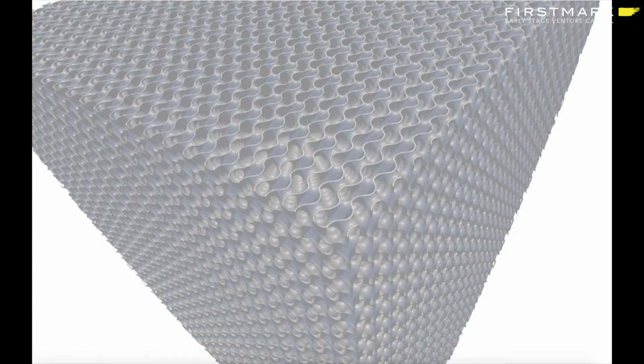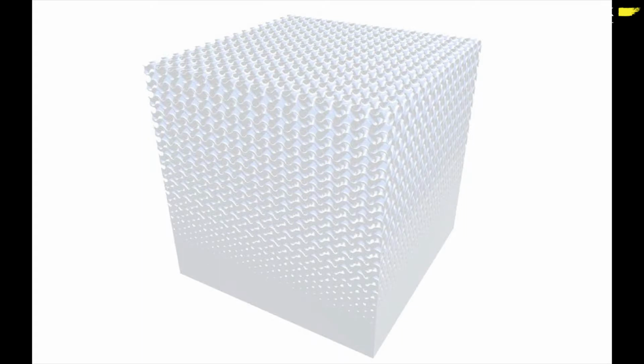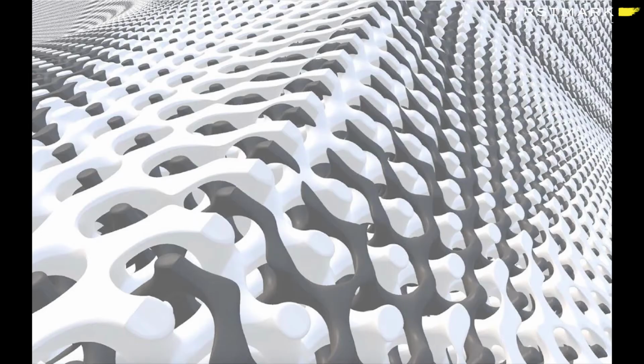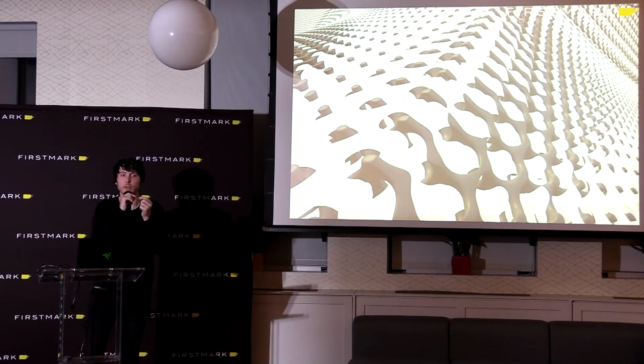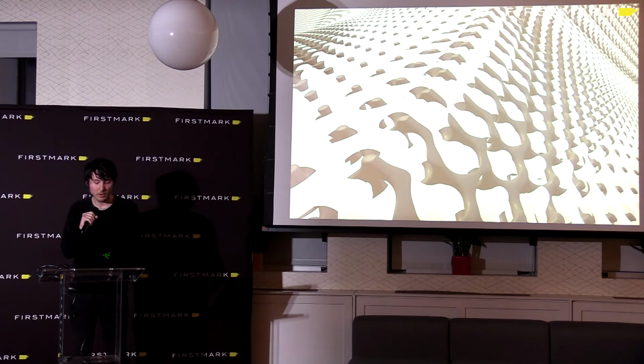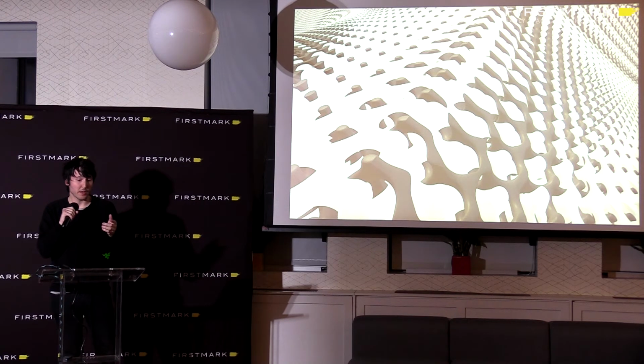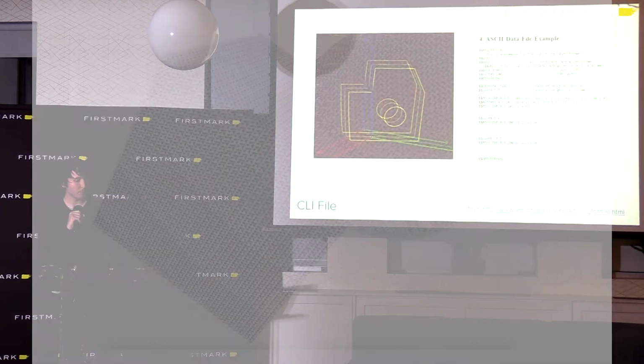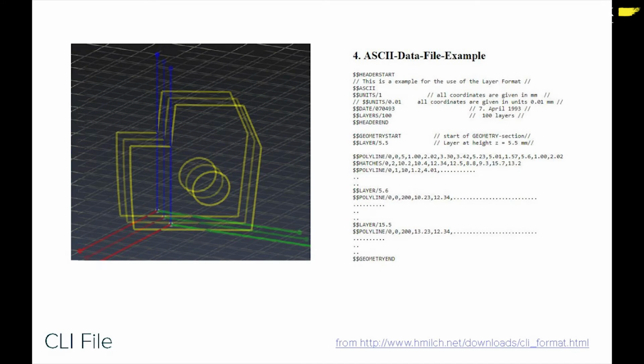And then we can also grade our structure. But something like this would probably be impossible to mesh, a structure where you have a 300 millimeter box with a 0.5 millimeter unit cell size. I think stuff like this can really start to enable detailed control of the design of really localized properties of a part, like controlling the cells of wood to make custom wood for you. Or we're doing a lot of work with the Air Force in terms of really customized material properties of lightweight metal parts.